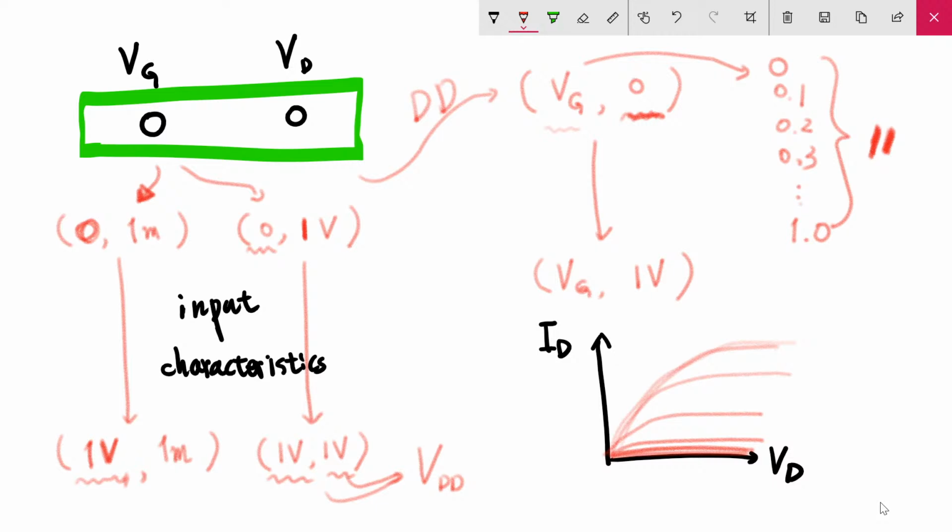Sometimes if we ask somebody to perform the device simulation, they just do this job or any other jobs of their own interest. Then I ask them, what is the threshold voltage of this one? Then they cannot answer, because with this output curve, maybe we can say about 0.3 or 0.2 will be the threshold voltage. No, threshold voltage is really an important quantity, so you should be able to say exactly what the threshold voltage is for a certain device.